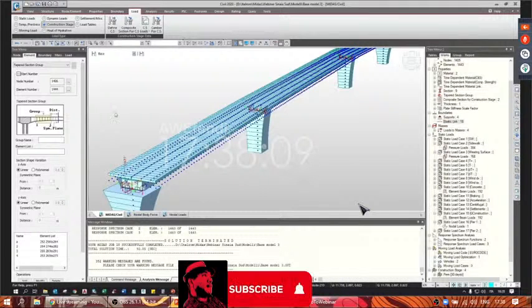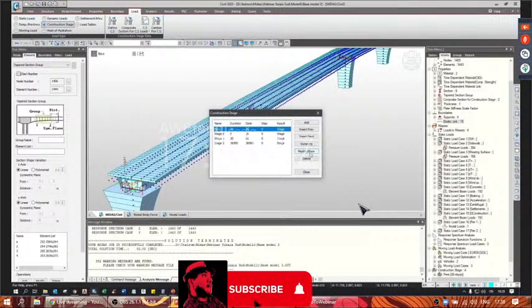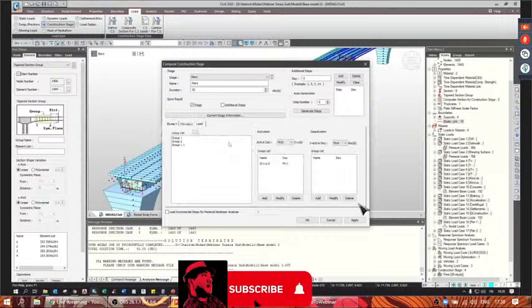Okay, now we analyze the construction stages. We have a first stage of the duration of 30 days. That is the time needed by the concrete to reach its resistance and become an effective element. In this phase, piers are built and the other spans of the viaduct are installed. We activated piers elements, fixed at the base as boundary, and the group of load 0, that is composed by self-weight and the weight of the lateral spans.